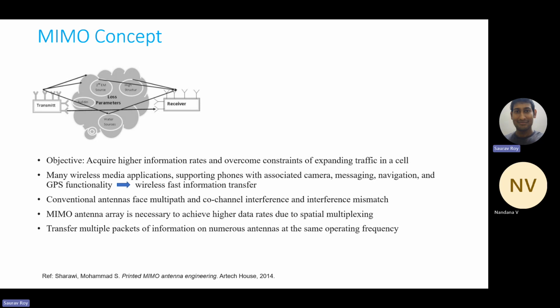So this is called spatial multiplexing. There are two things here. Let's say we forget about the data rate, and even with one antenna, whatever error happens is acceptable. If the error is acceptable with only a single antenna, then we can send multiple data, not the same data, with the multiple antennas. If we send them in parallel, it will increase the data rate.